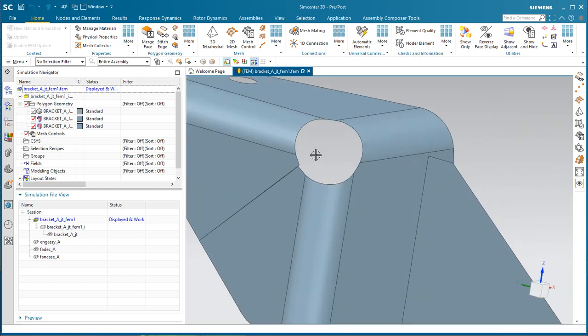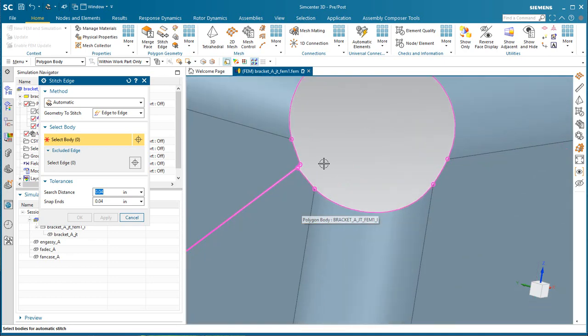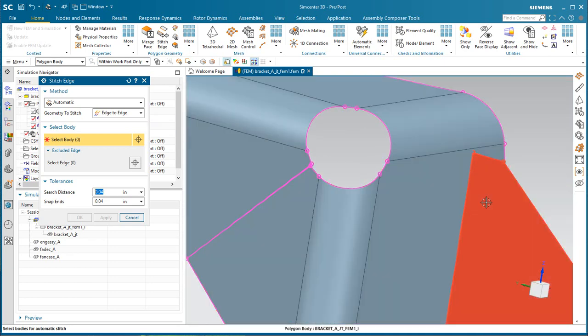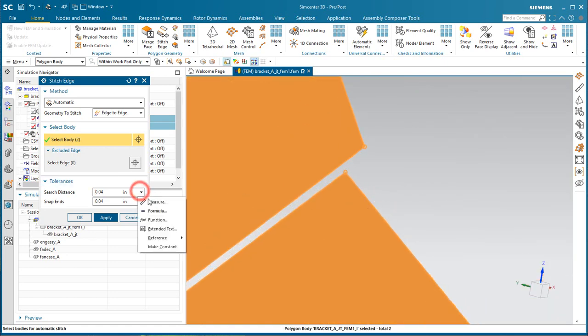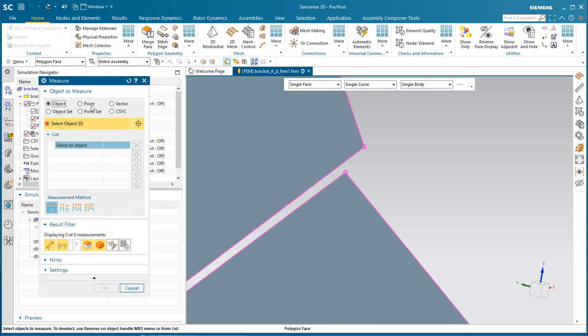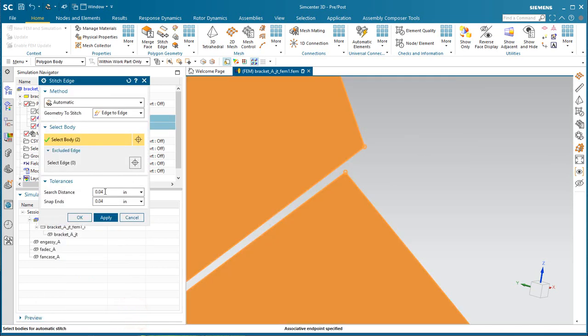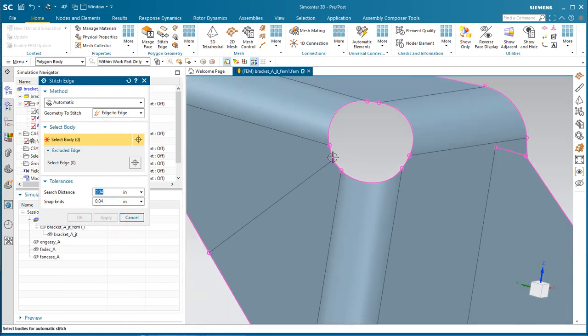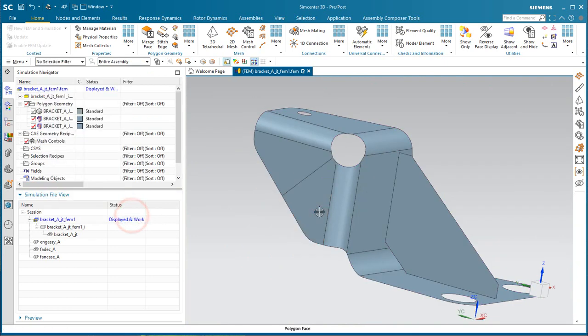So we'll bring the geometry for the mid-surface and the solid into the FEM, where we'll stitch the model together. This will allow us to fix any tiny issues with the geometry, as well as ensure a congruent mesh across the various bodies. Here we'll take a distance measurement to see just how much slop there is in the model. So 40,000 should be able to take care of that 17,000 slop, and here you can see it does, as well as ensuring a congruent mesh across the gusset.